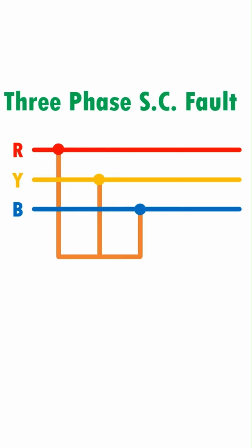The three-phase short circuit fault occurs rarely, but it is the most severe type of fault, which involves the largest current. This large current is used for determining the rating of the circuit breaker. The probability of occurrence of such type of fault is less than 1%.